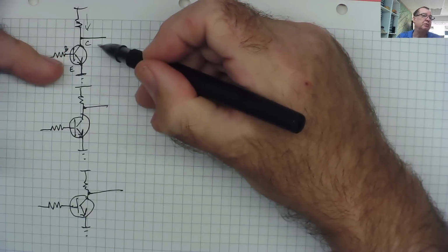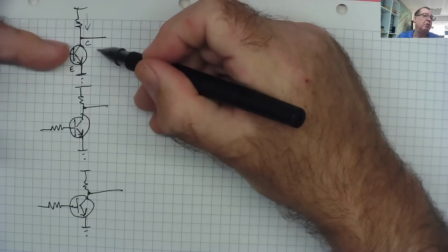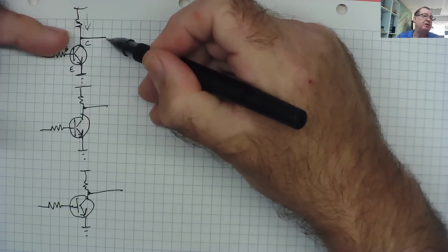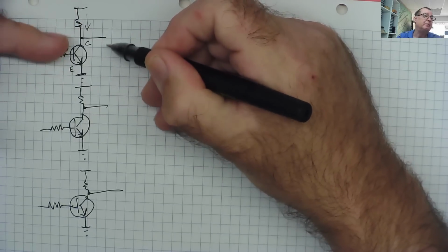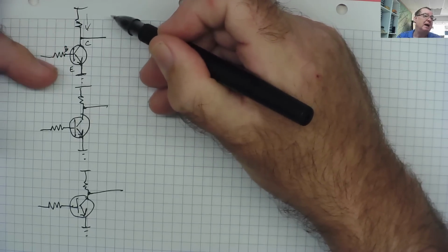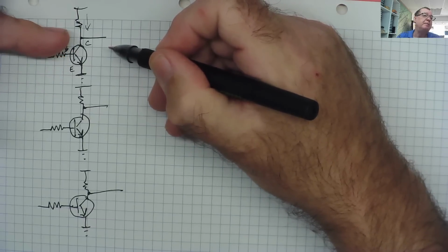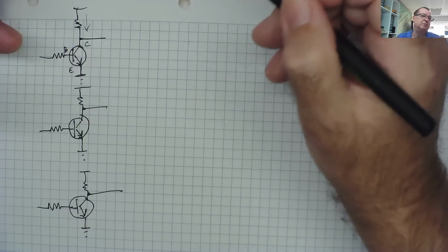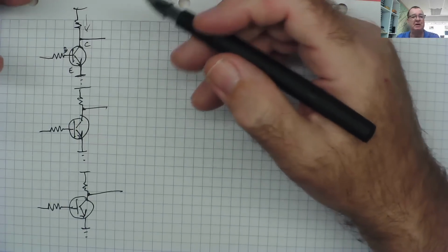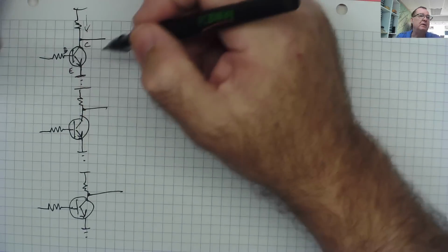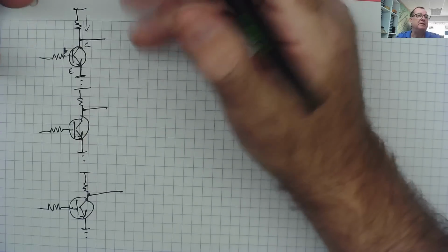Yeah, as you alter the voltage down, it will go up. As you go up, it will go down. So the voltage on here will vary as you vary that voltage, and notice it varies in the opposite direction. The more positive you make this, the more negative this becomes. That's basic transistor operation. But we want to make this work in a digital fashion.